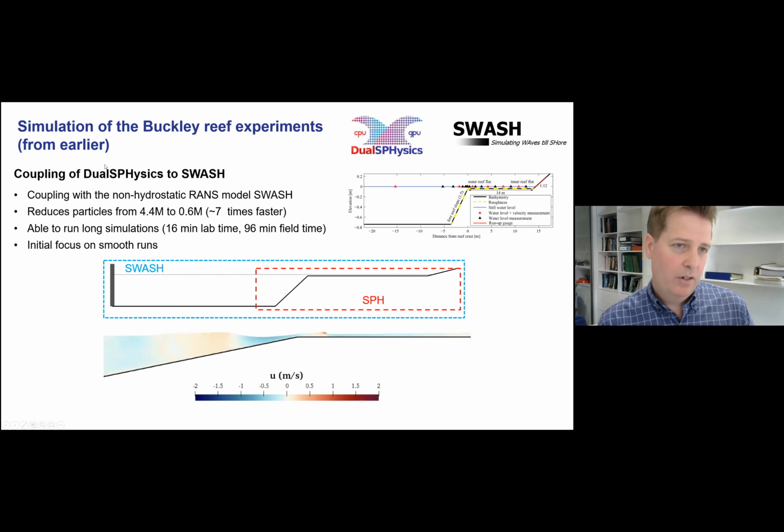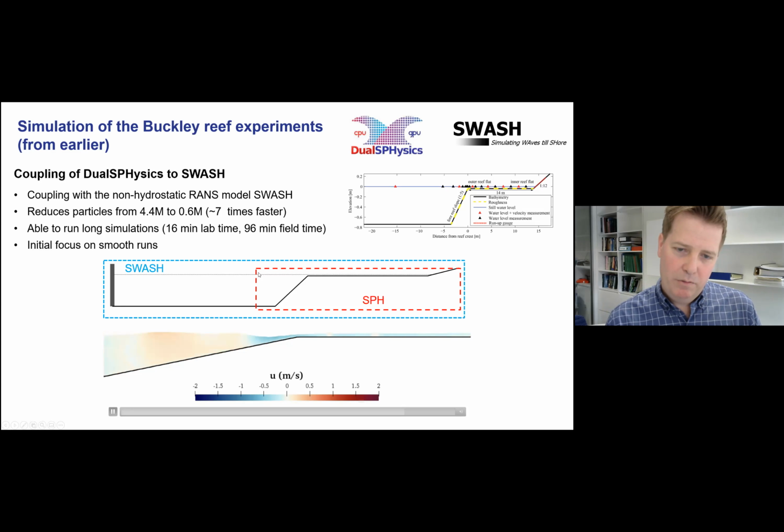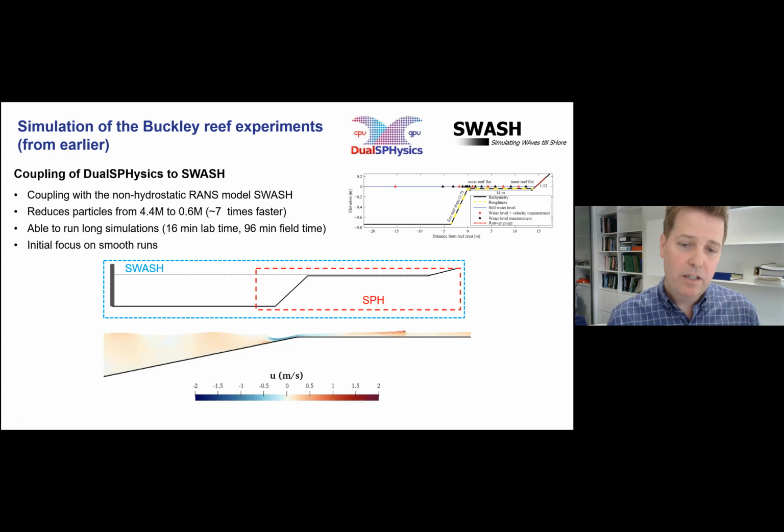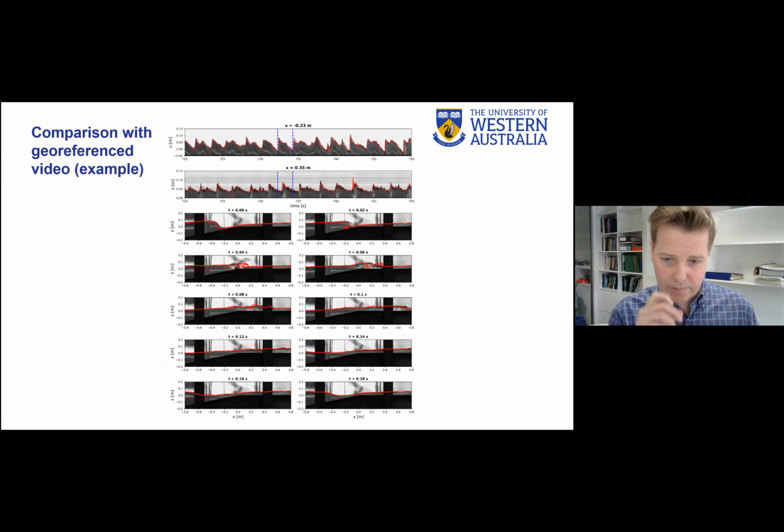And so with a group, Corrado Altomare in Barcelona, we've been working on new approaches to couple this DualSPHysics model to SWASH, where we essentially run SWASH over the full domain, and then we focus just on the fore reef and the reef flat with DualSPHysics. And so now we can actually run these highly resolved simulations for very long periods of time, getting thousands of waves and also getting irregular wave conditions.